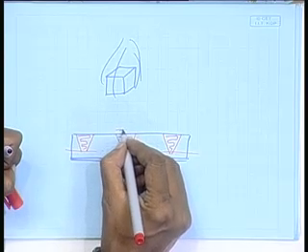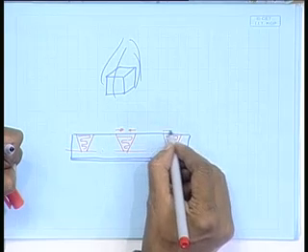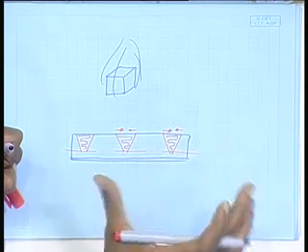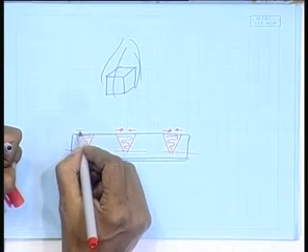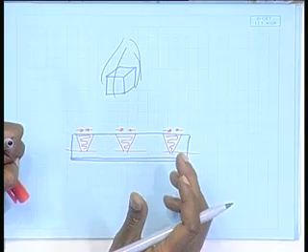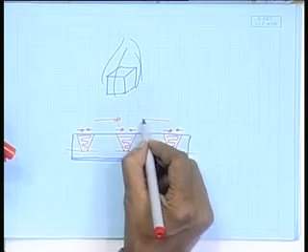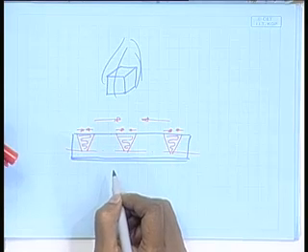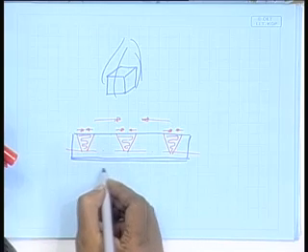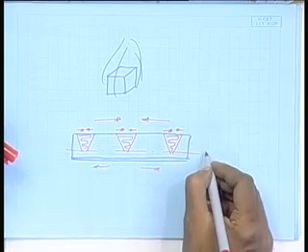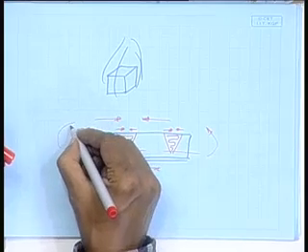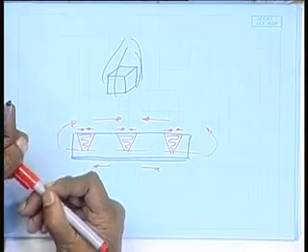Shrinkage here will take place. It will shrink because of that same mechanism of shrinkage. If it shrinks, then a cumulative shrinkage force develops. If that is happening below the neutral axis, a tensile force will develop, will give rise to a couple, and it will bend, right. So that is how one can do the bending of frames.